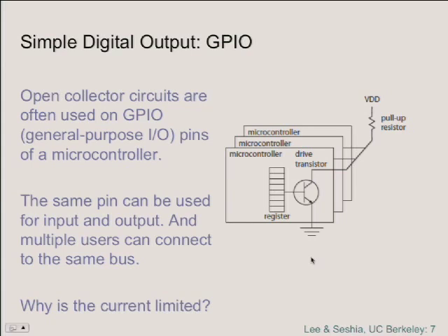Okay, so that's one mechanism. That's a simple response mechanism. So if you want to hang a passive device that simply has memory mapped registers, that's how you do it. You just listen for your address. When you get your address, you assert your value on the data bus.